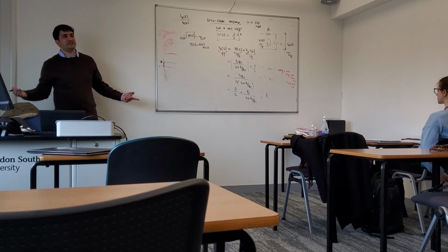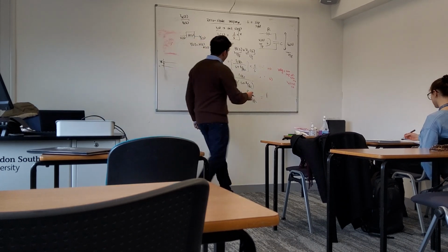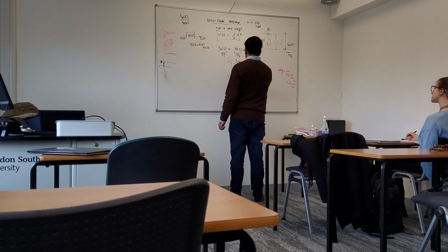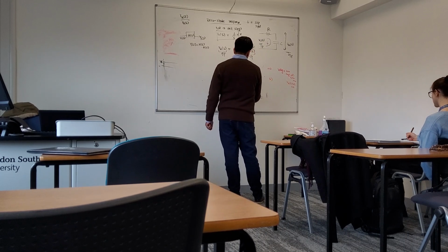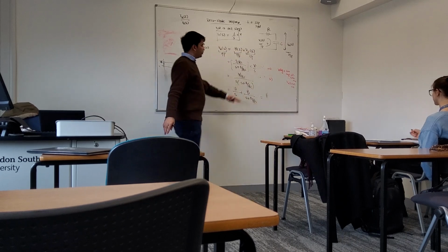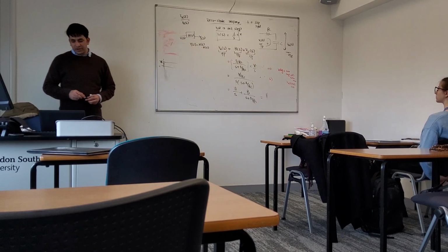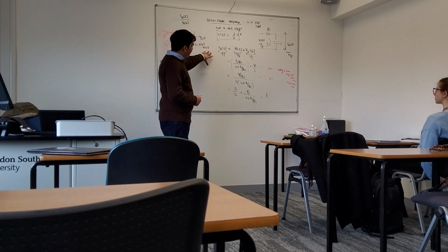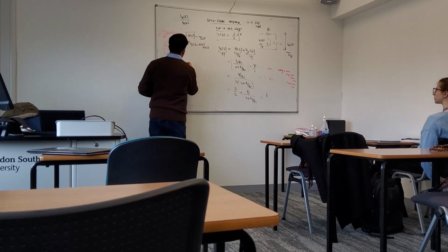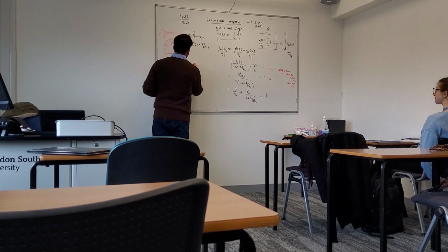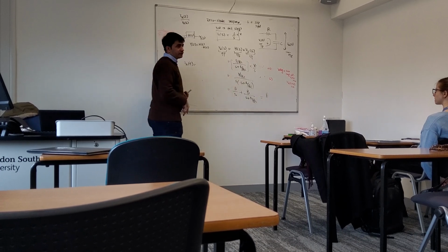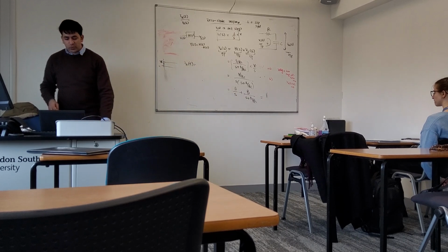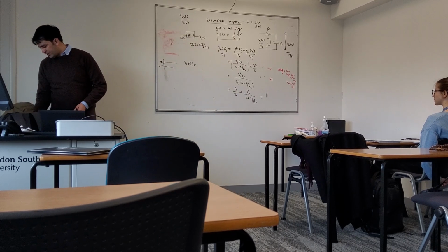It has any magnitude, any V, right? So instead of 1 here it is V by s, V by RC, and finally when we're going to solve it, we will get it in terms of V. Okay. So if I want to find V2, V2 of t is the inverse Laplace transform of this function, considering that we know the value of A and the value of B.